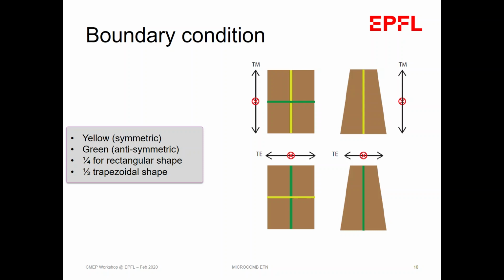Second question: what is the mathematical definition of adiabaticity in this context? Mathematically, how can I define this? What condition do you have to fulfill? I also know that if the taper is longer than 100 micron, it shouldn't make a difference. I think it's about the mode overlap with the mode in your bus waveguide. The less the mode changes its shape inside the taper, the better the overlap. So the change in effective index per unit length is smaller than 1.